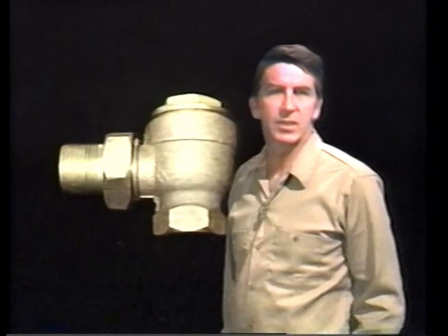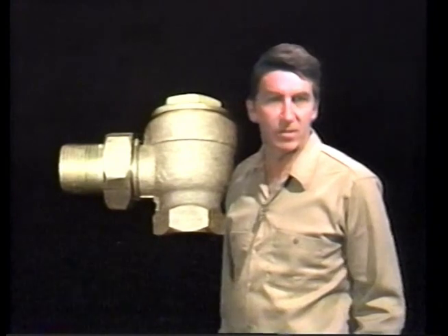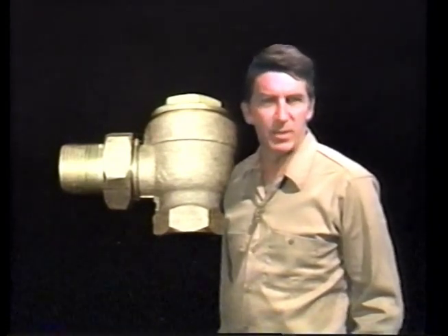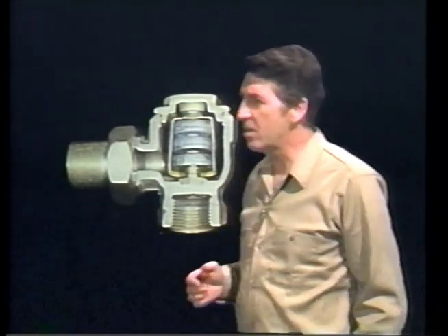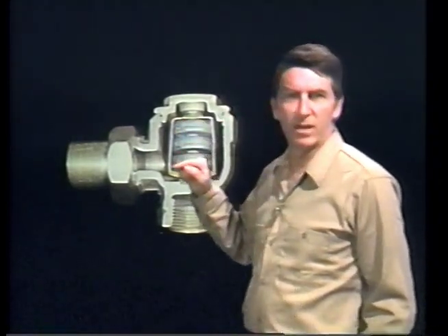Because the bellows-type thermostatic trap gets rid of air so easily, it's ideal for situations where large quantities of air are present. But these traps are limited by pressure. Typically, they cannot be used where the pressure is very high. If they are, the bellows may collapse. Another trap limitation is its susceptibility to water hammer, which can rupture the bellows, causing the trap to fail open. Some bellows traps have a shroud or covering around the bellows to protect them from water hammer.